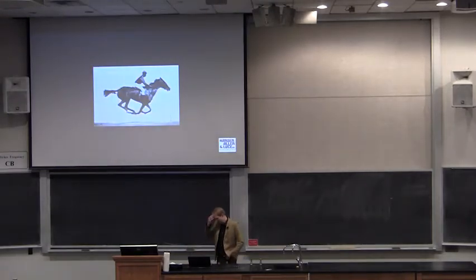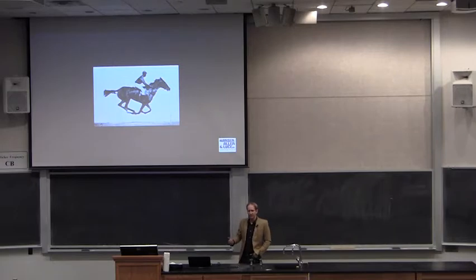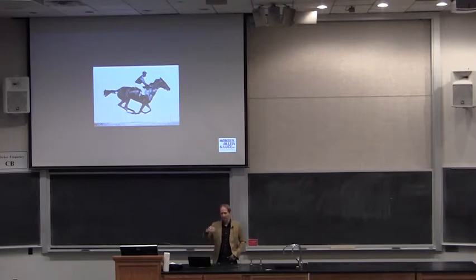So here's my little example of extended period hydraulic modeling. At first, when I first started, most of the hydraulic modeling was static. So you'd pick a worst case scenario, low pressure time or high pressure time, and you take a snapshot and kind of assess what's going on. It gave us some data, but it's not as powerful as extended period modeling.